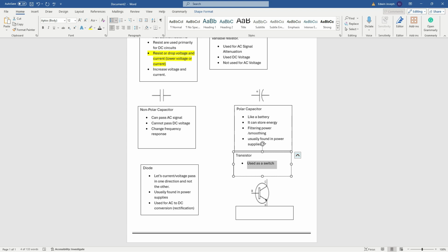But what a relay does is it takes the voltage that's applied to a coil that moves some kind of magnetic switch that then completes the circuit. But it's mechanical, just like the switch on your wall. A transistor is not mechanical. It's completely a switch just by virtue of how you set up the voltage in it. And I'll show you why here. The next one will be turned on by 0.7 volts.